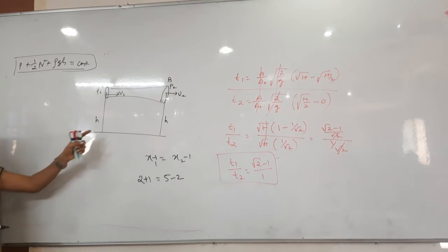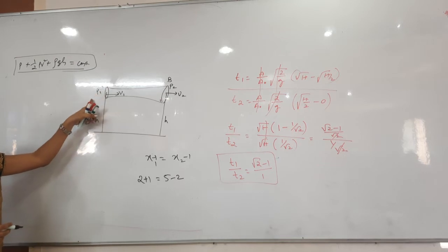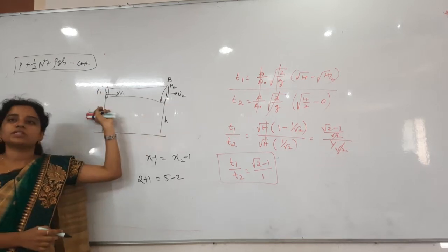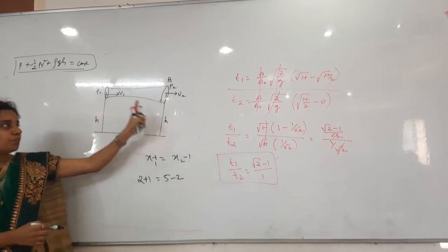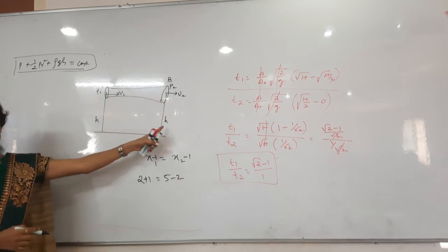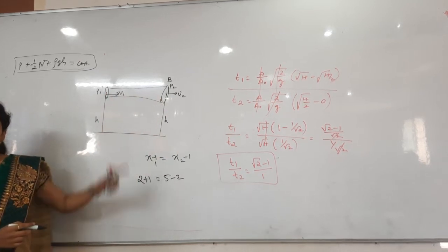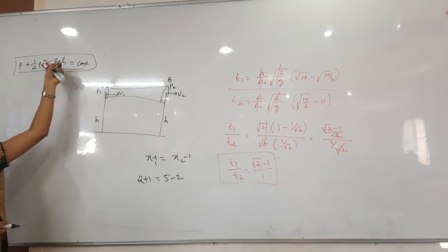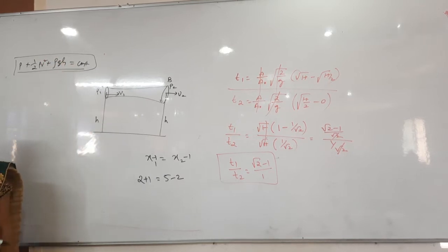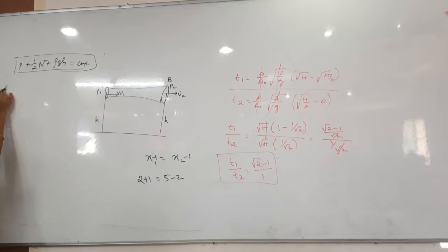Now I have taken a water pipe of different areas and having different velocities and different pressures. Both the holes are at the same height only, h is the same. So rho gh will not be there, rho gh difference is not there here. Otherwise I can apply normally also. Apply Bernoulli's theorem at A and then B. At A, tell me, what is the pressure we are having?